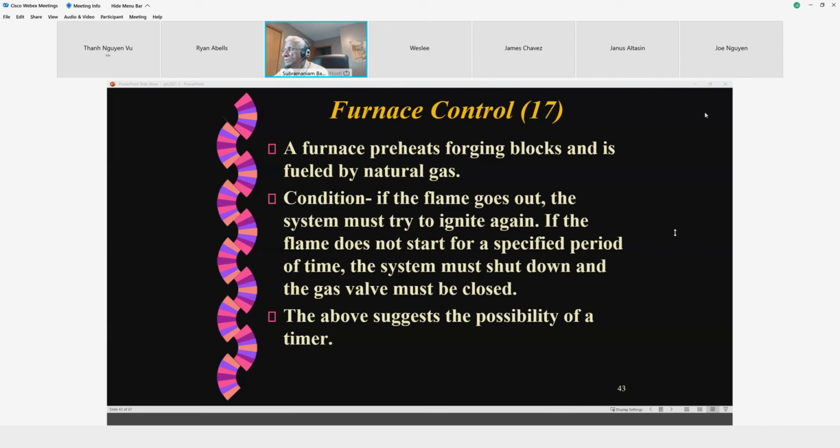Okay? So when it comes to higher speed, it extracts the heat. The room temperature goes up. Now they will shut it down at 20.1. The older controllers will go 22 to 18. It has a wider swing. The newer ones come in pretty quick. Okay, it shuts the system off.